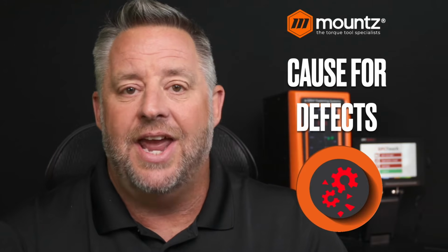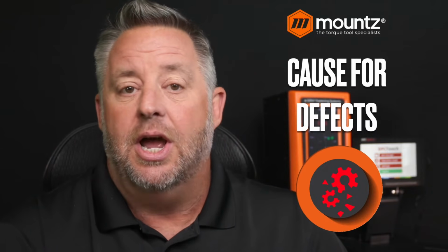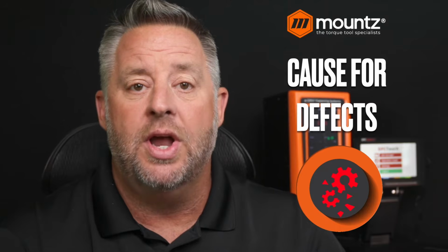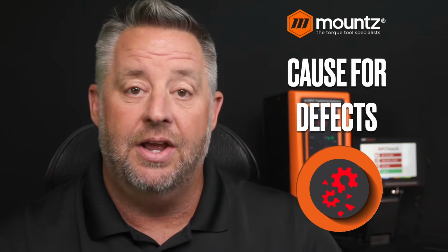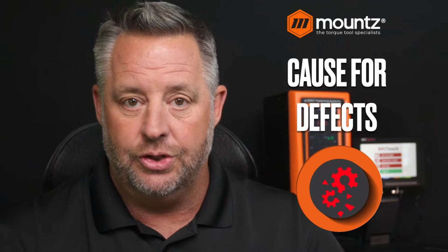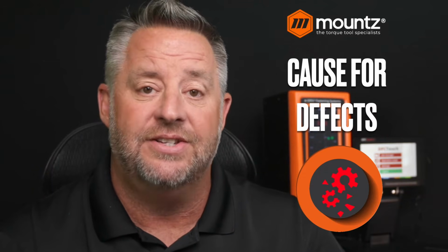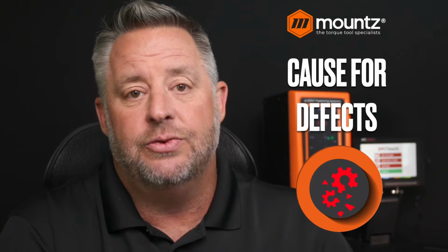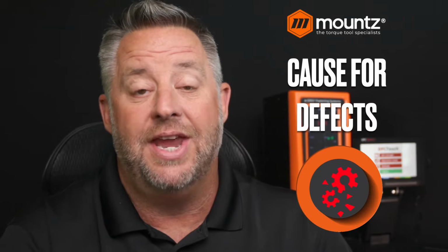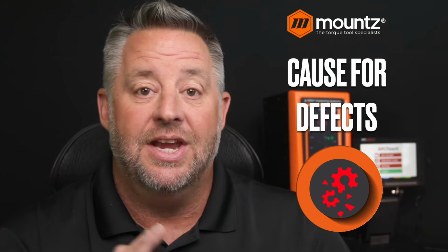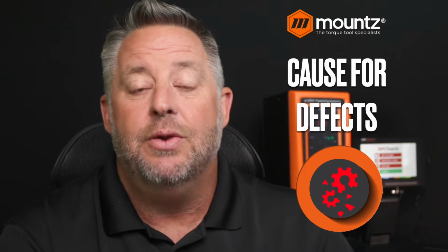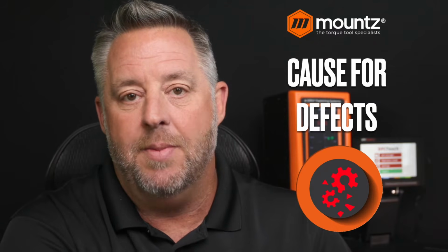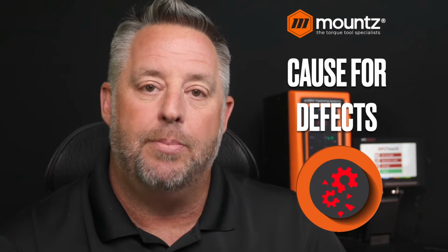And so when we look at causes for defects in the assembly process, the number one most often defect is going to be caused by the operator, or a human influence in the actual defect that takes place. And so if we can, again, as we talked about, and we will talk more about the error proofing aspect of the assembly, if we can control what the operator can and can't do, then we can help to minimize the different defects that we might see within an assembly operation.